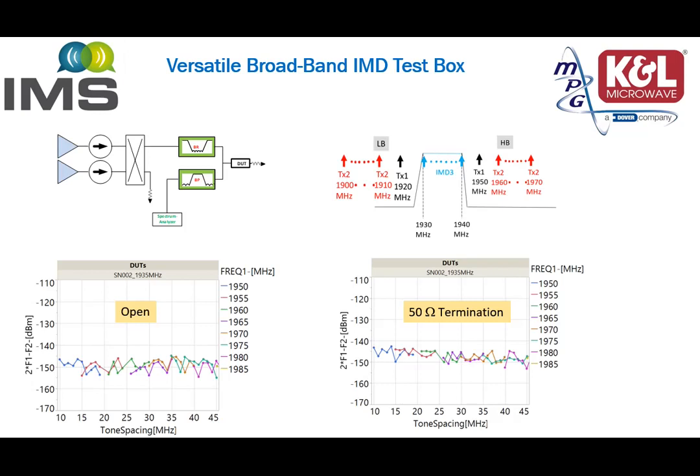In the diagram on the left, there is a low-cost, broadband, and easy-to-install combining network. Two amplifiers, each providing a TX signal, are combined via a 3 dB hybrid quadrature. This 3 dB hybrid quadrature must be a low PIM device. You need to specify it up front. We then pass the combined two signals into a band reject filter, which is connected to a bandpass filter in cascade.